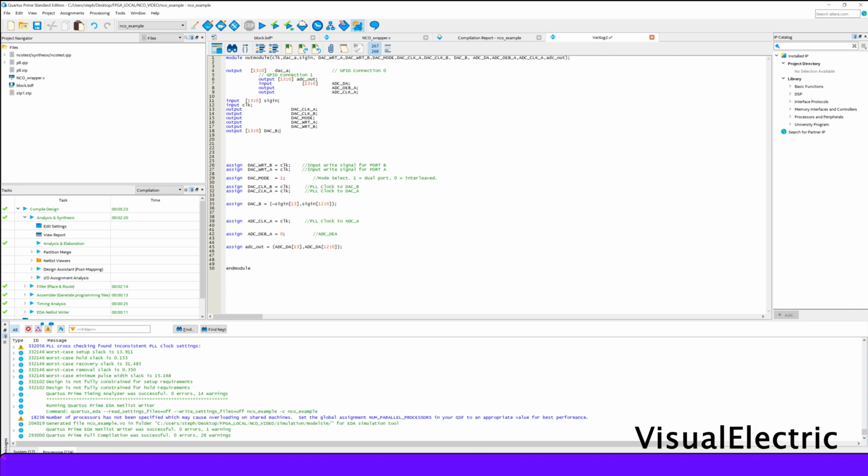For this one, we're going to output 14 bits on this output port here. Those 14 bits have to go to 14 pins, and those pins need to be chosen so they target the right pins on the connector, so they ultimately go to the digital to analog converter. So that's going to happen there. There are also a couple of control signals for the DAC, DAC write B and DAC clock. Both of those will be derived from the 100 megahertz clock, which already exists within our project.